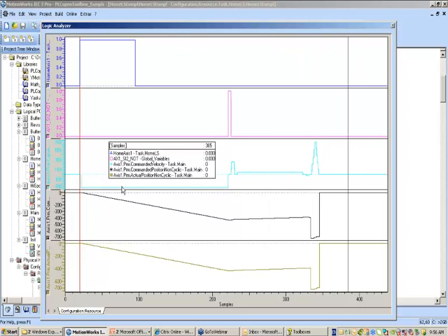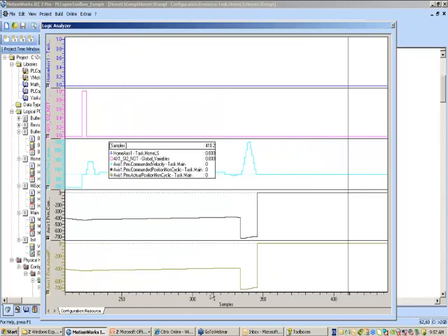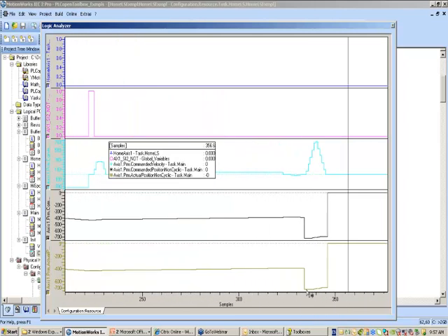And then it found our end of travel limit, and it did a little bit of a backup move just to get off that limit. So it reversed direction. So this move is a positive move. Then it started creeping in the positive direction until it found the C channel, at which point it went back to the C channel. So if you notice here, you can see just a little bit of a negative velocity. That's because it does actually stop, back up, and return to the position of the C channel. And then it makes its final offset move forward and sets position to 0.